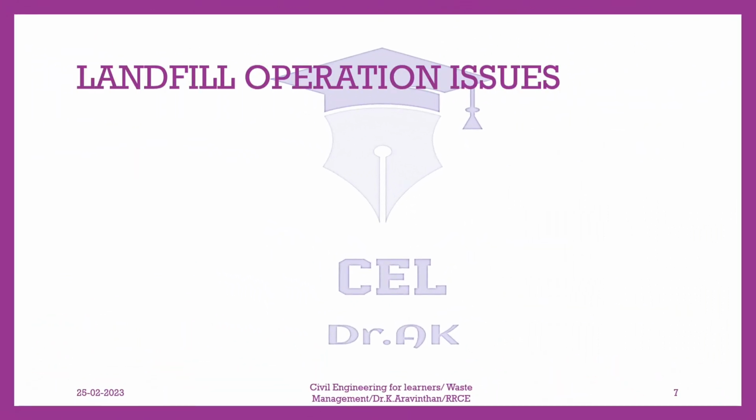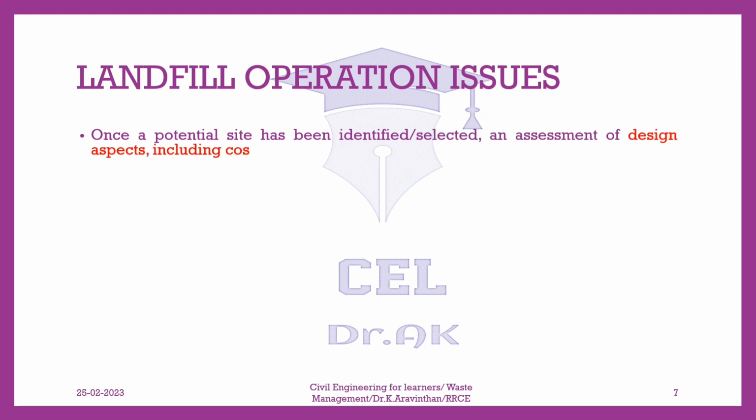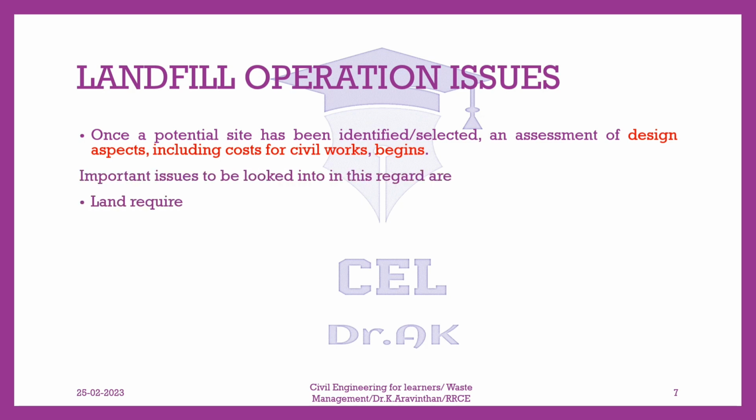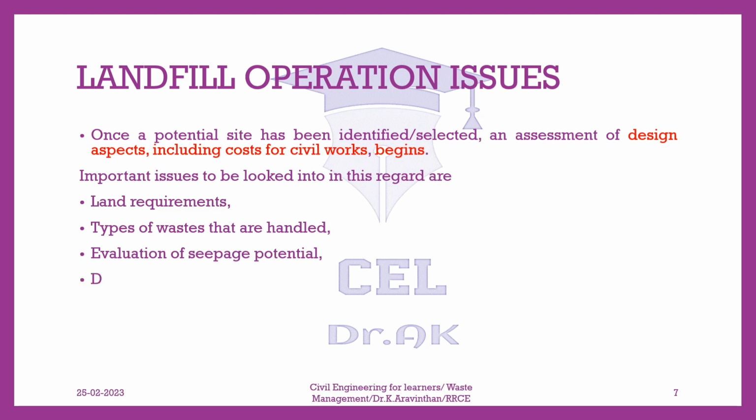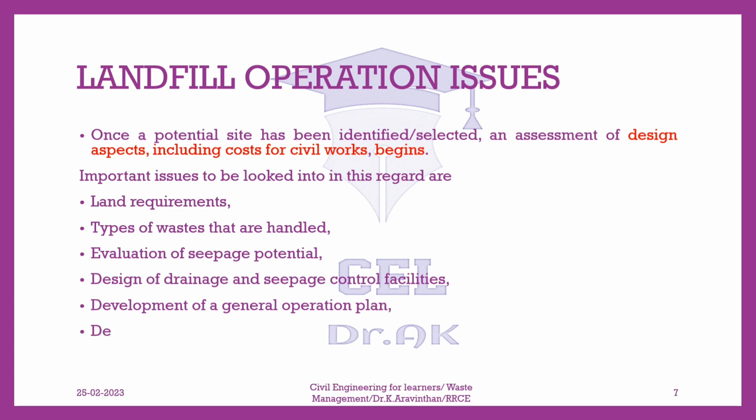Landfill operation issues. Once a potential site has been identified and selected, an assessment of design aspects, including costs for civil works, begins. Important issues to be looked into in this regard are: land requirements, types of wastes that are handled, evaluation of seepage potential, design of drainage and seepage control facilities, development of a general operation plan, design of solid waste filling plan and determination of equipment requirements.